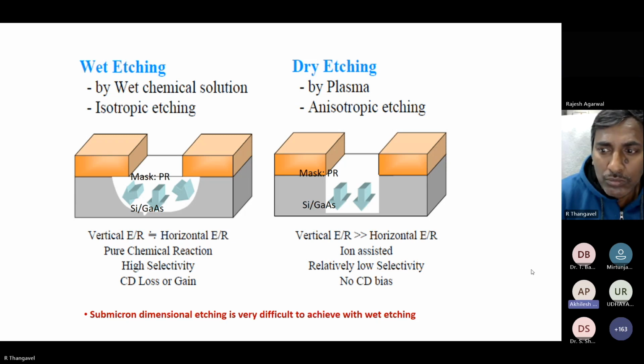In wet etching, the process involves transport of the reactant to the surface, followed by surface reaction. The advantages of the wet etching process are low cost, reliability, high throughput and excellent selectivity. There are also various disadvantages: it is very hard to control the critical features, difficult to control the degree of over-etching due to undercut, and the etch rate decreases as the reagent solutions are consumed.